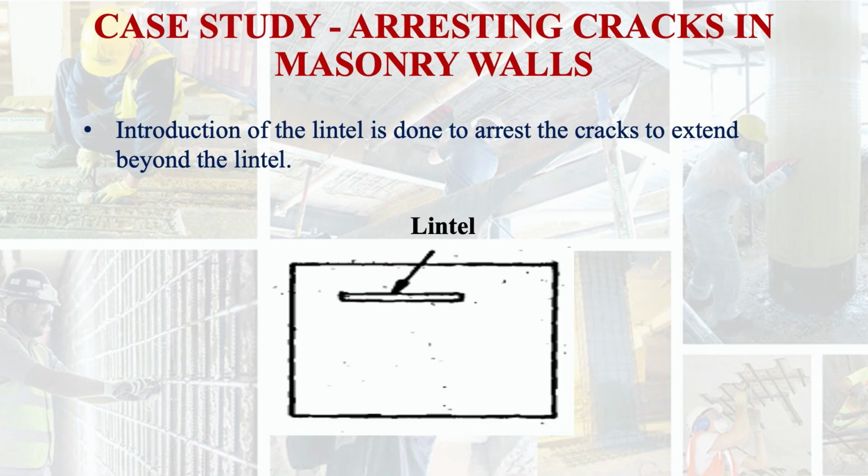What is the nature of the cracks? You see mostly the diagonal cracks here. So introduction of the lintel is done to arrest the cracks from extending beyond the lintel. So as you see here, that lintel can be provided in the wall to arrest these cracks.